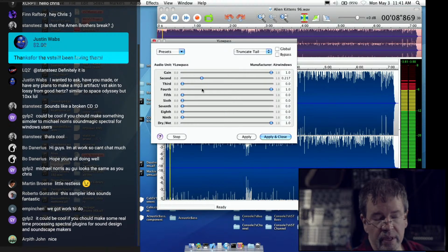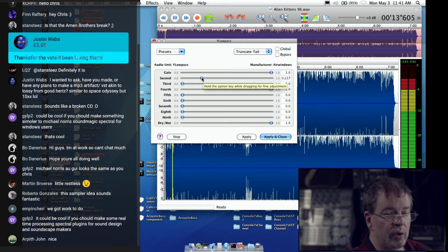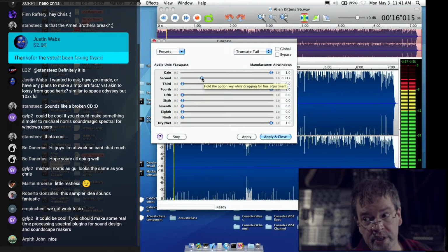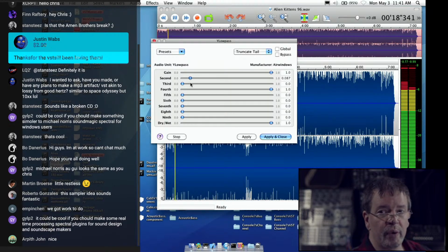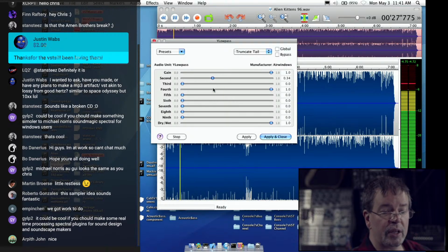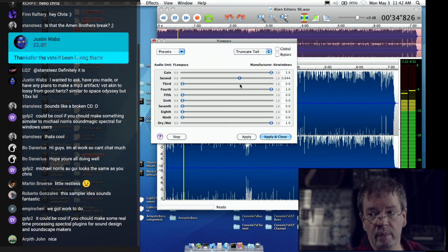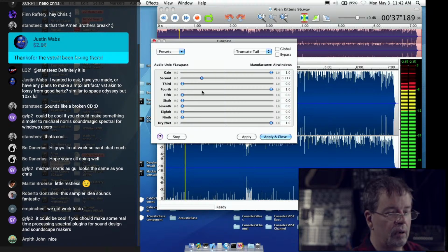this kind of thing, where it's your Airwindows sine-based overload run inside the actual filter, inside the feedback element. Now, the way that the EMU does it is it's a straight-up hard clip. It's a straight-up aliasing hard clip, and apparently people liked the way that sounded. And it's worth finding out what was going on with that so that I can try to model it. But this does make neat sounds on its own.